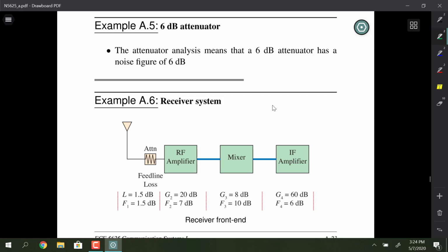I was talking about that yesterday in my phase lock loops class, and we were going through an example of a GPS patch antenna, and then you have something called a bias T that sits at the receiver. The bias T allows you to interject DC into the coax, but keep it isolated from the receiver front end through a blocking capacitor. And then the bias is fed in through a decoupling network to make sure that the RF impedance match doesn't get disturbed when you feed the DC into the cable.